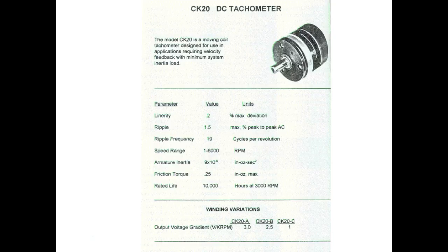as tachometers, or something called tach generators for short. We do use them a lot. So these spin permanent magnets because we don't want the magnetic field changing. So what would determine how much voltage we get out of these things? Strength of the magnetic field, which we're not changing. The number of conductor loops, we're not changing. So what's going to determine the amount we get out here would be the speed of the motion.